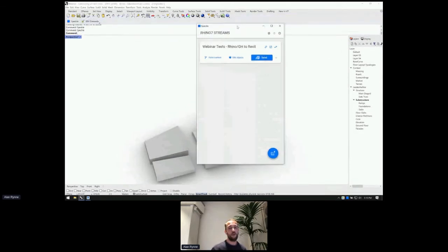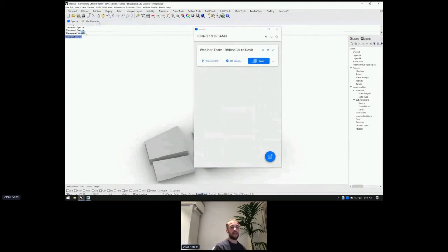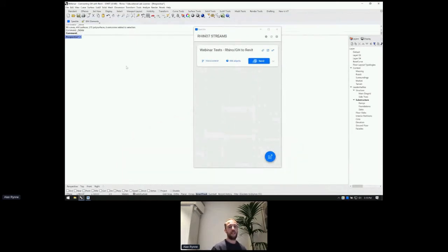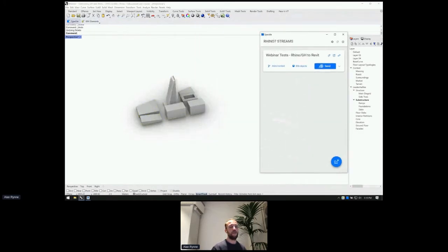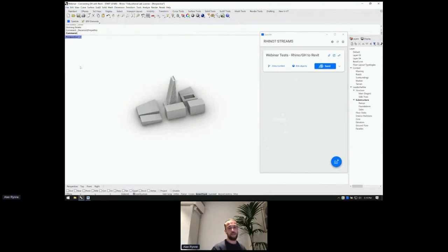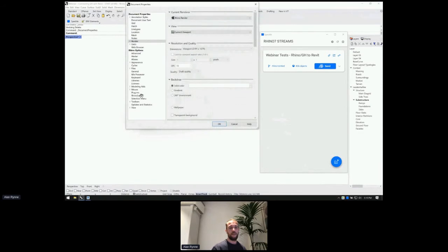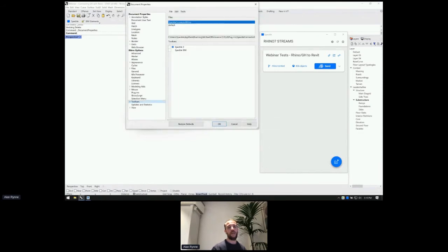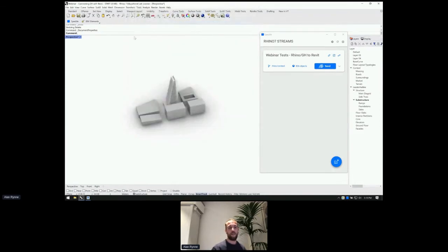So if that is okay, then that means that your install should be working properly. If your install works properly because you ran your speckle command, but you didn't see your toolbar, you may need to activate it by going to your properties, the toolbars menu, and there should be a Speckle Connector Rhino option that allows you to activate these toolbars individually. So that's just a quick tip if somebody is missing these buttons that I will be using quite a lot.